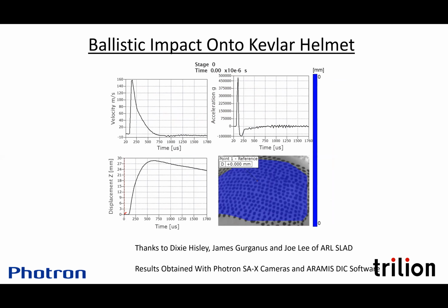It's intrinsically sensitive to velocity, and velocity is high as frequency goes up. Scanning laser vibrometer is great for very high frequencies, and it also has that interferometric level of sensitivity, so it can do very high frequencies with low amplitudes.